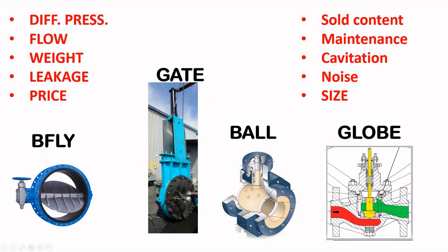If you have fluid which carries some solids with it, like slurry, the type we use is the gate valve, because when you open it, you actually release the gate from the body and there is less erosion and damage to the valve.